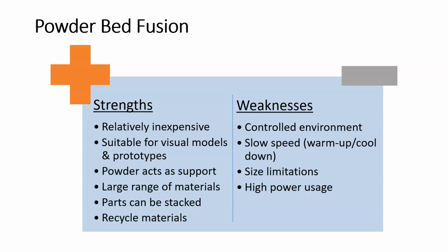Some of the weaknesses are you need a completely controlled environment. That means you have the build area, and the entire machine needs to be controlled. So the build area, the reservoir, is going to be heated, and you also will need to heat the supply of powder, whether it's plastic or metal. That area needs to be heated, so there's not a large temperature difference between the supply and the reservoir where you're building.